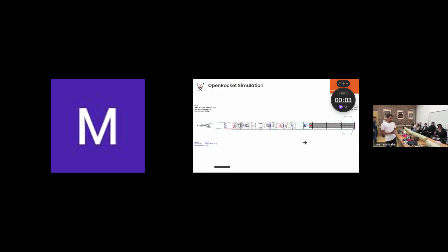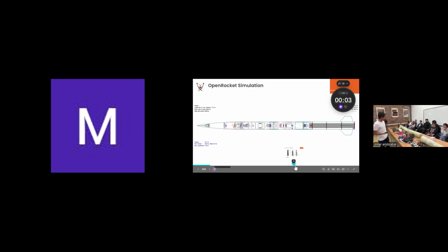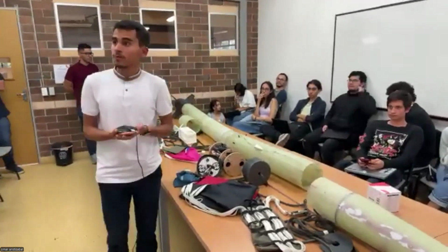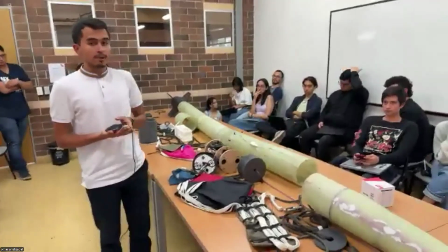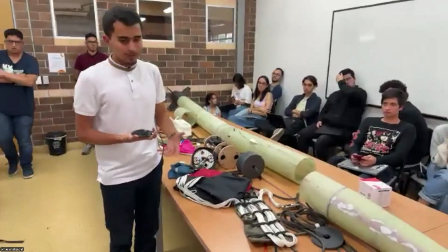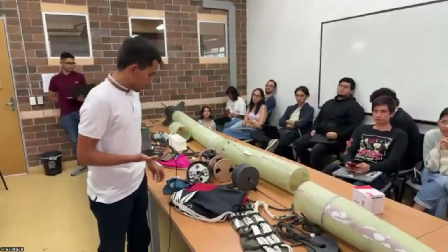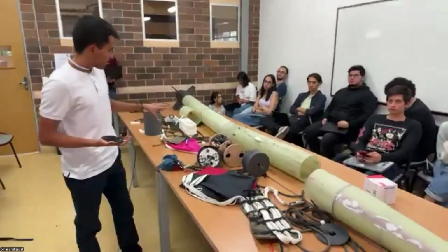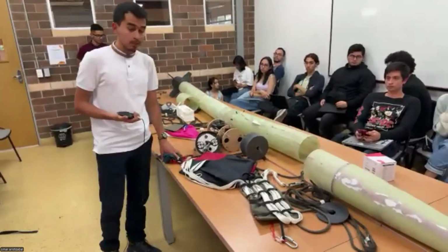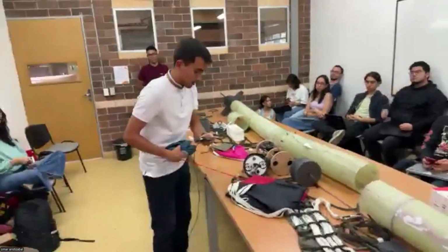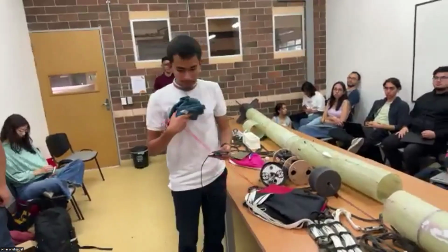Regarding parachutes, there is something I would like to add. These COTS parachutes are actually planned to be used as a backup, because our main objective is to fly with SRAT parachutes, because of the encouragement of ESRA to use SRAT components. Currently, out of the 3 parachutes, we have developed the pilot chute only. We are currently manufacturing the drogue and main parachute, but they are still not ready.